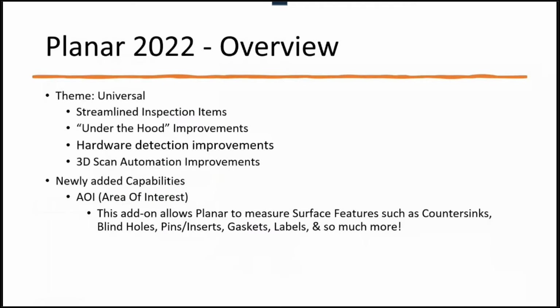This allows you to measure planar features such as countersinks, blind holes, pins, inserts, gaskets, PEM nuts, some labels, and kind of anything else we can see while using the light from the top of the part, filtering it out with creating a shadow. Thus, we can measure where that feature is at. So that will be discussed at the end of this video, as that is one of the accessories that people don't really have yet, but I just want to show it off and its capabilities.